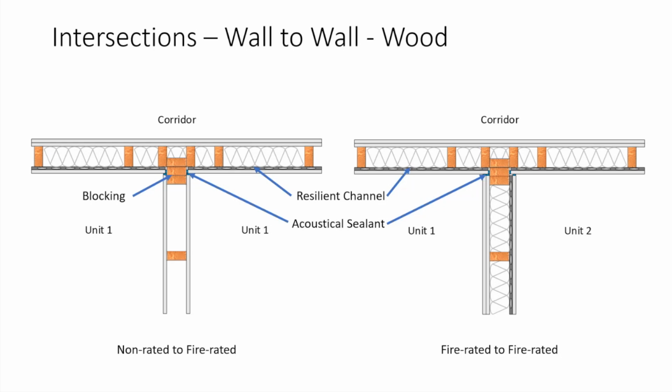In wood frame construction, you can use a wood stud as fire blocking. So it can interrupt the fire protective membrane, the gypsum board. You can start and stop your gypsum board at this intersection, right? You start and stop it, and then you have this.